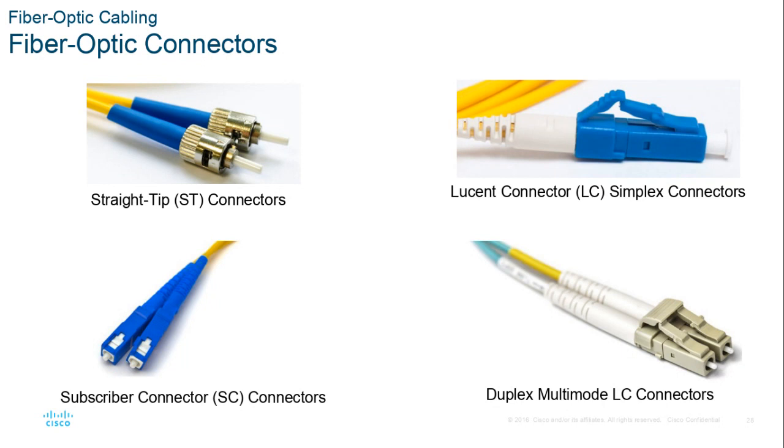With the SC connectors and the ST connectors on the left, it's possible to plug them in incorrectly. Transmit to transmit, receive to receive. And if they don't work, you just have to unplug them and plug them in the other way. So future proofing or idiot proofing, I like the ones on the right.